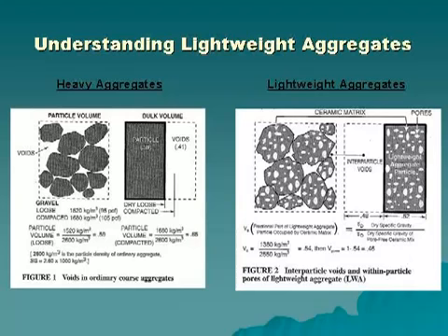In the graphic on the right, depicting lightweight aggregates, we have combined the ceramic matrix and the pore network in a graph structure. In this example, the combination occupies 52% of the volume, leaving 48% of the volume occupied by the interparticle voids. This interparticle void network is where the glue is distributed, holds these particles together. This glue is actually the cement mortar, which is comprised of water, Portland cement, and finer particles.